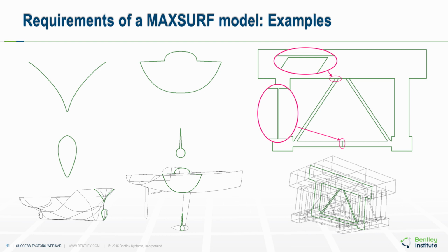In these examples we can see a container ship with a bulbous bow, and again we have one completely closed contour and another contour which is open, which will be closed with a straight line. The middle one shows an example of a yacht where we have completely closed contours, including the deck and coach house, and a part of the section through the keel and the keel bulb.